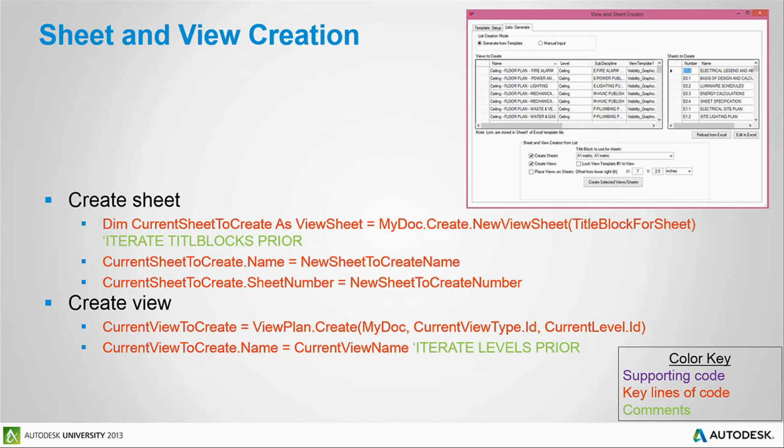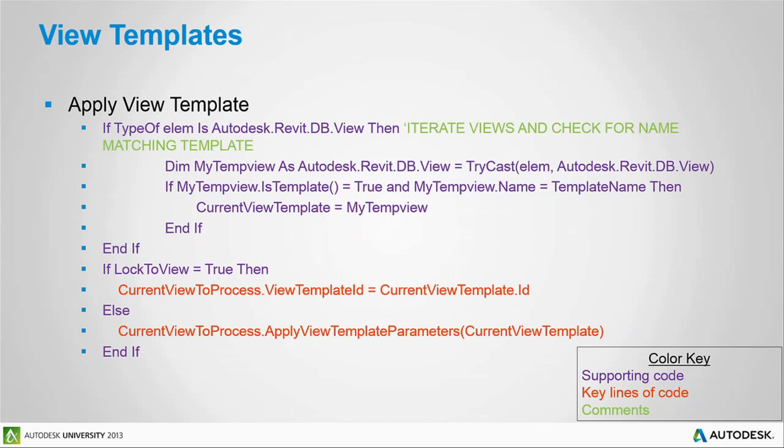Question: can I assign the view template, the scope box, positioning of the view on the sheet, all that? Can you assign a view template? Can you assign a scope box? Can you assign position on the sheet? The answer is yes, yes, and yes. So the next slide here is view templates.